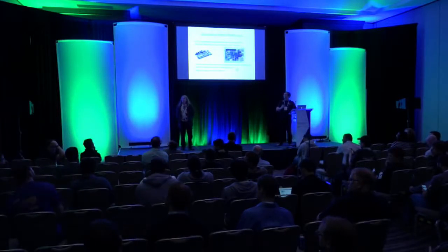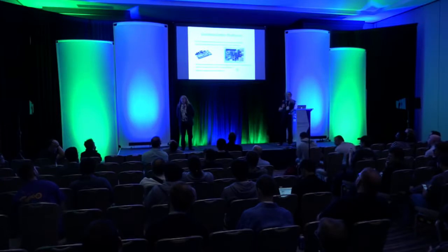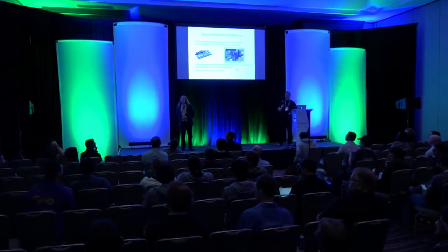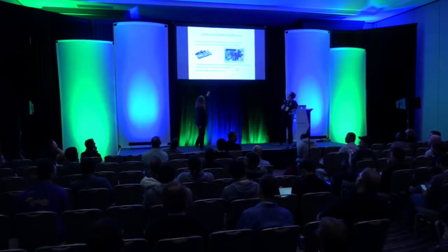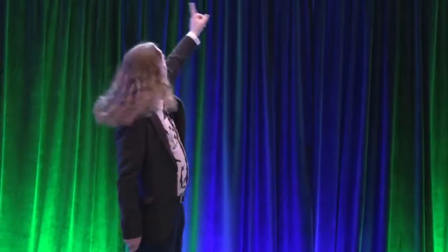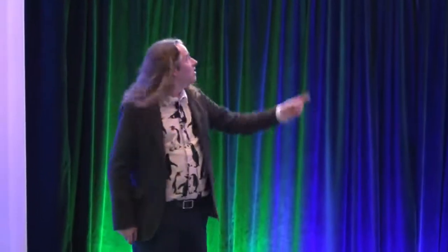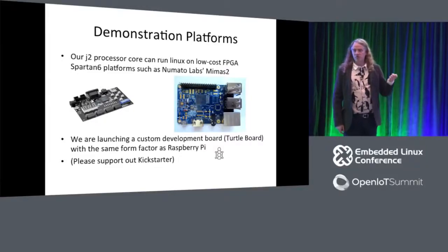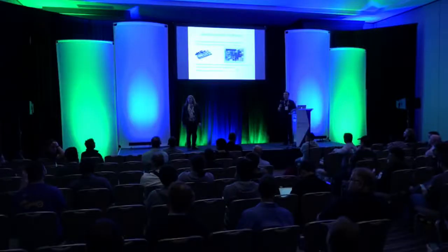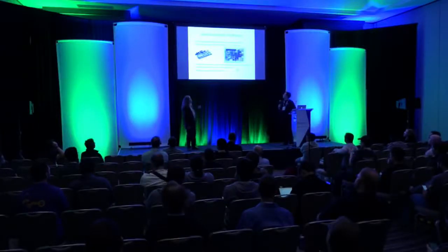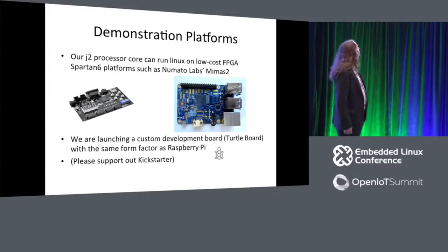I see that there is the USB port, the USB client. Four of them. It may be used to only power the board, or I may also implement the USB device. So the one down here, bottom left? The bottom left is the console, if you want it, or you can use it as USB UART. And the ones that are normally host are also host. There's a USB hub on board, and the FPGA implements USB 1.1. So it's the host mode, and I'm talking about the device mode. Device mode is not implemented.